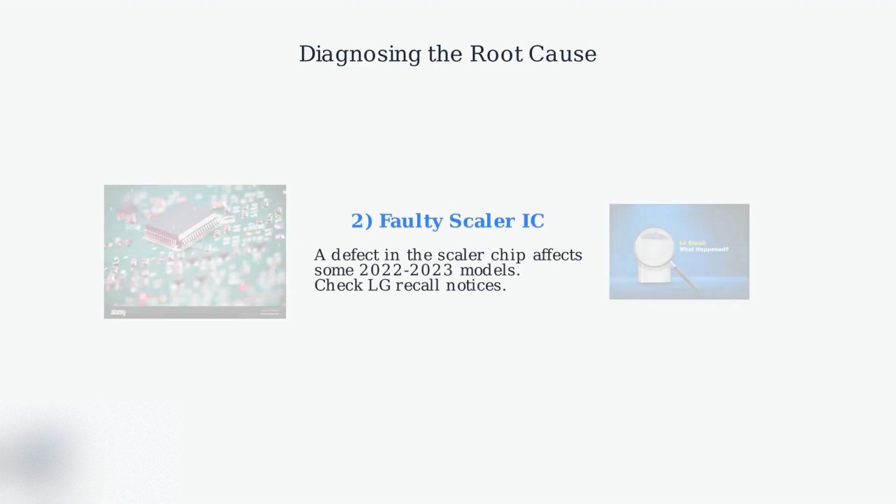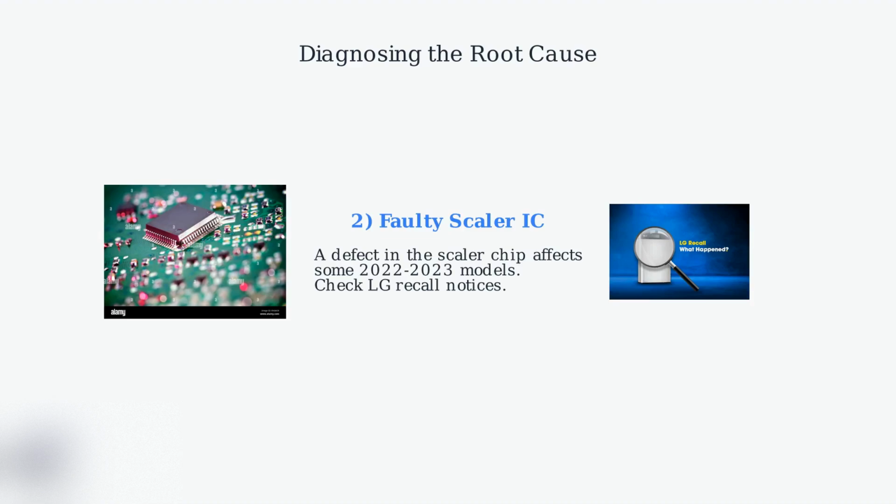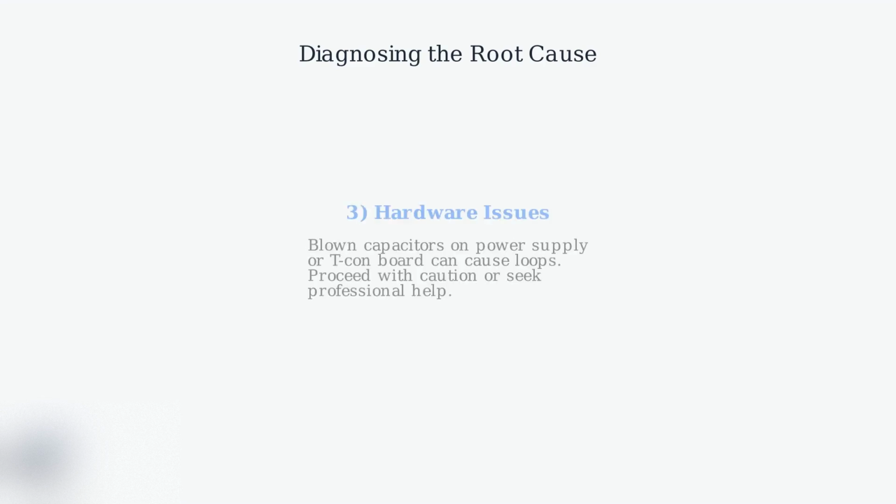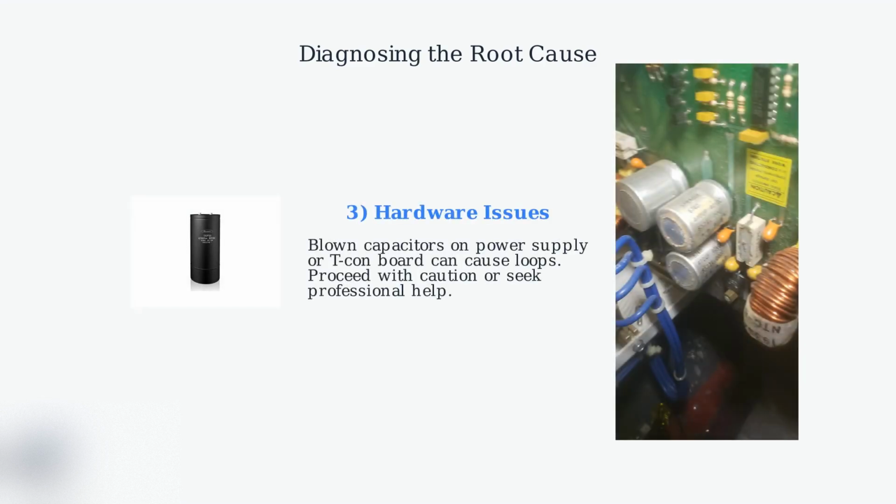Another cause is a faulty scaler IC, a defect in the scaler chip found in some 2022-2023 models. Always check LG recall notices for your specific model. Hardware issues like blown capacitors on the power supply or T-Con board can also trigger the loop. If you suspect hardware problems, proceed with caution or seek professional help.